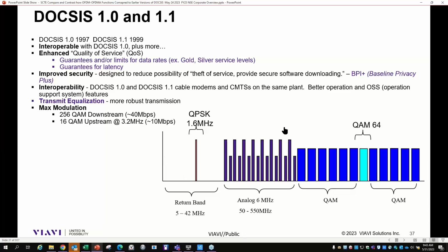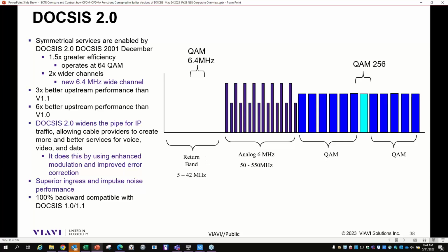Some systems used the upstream for video services, for analog, sending a video carrier upstream to another location and up converting those type of things. But primarily this was the DOCSIS capability of that, right? And then over time, the carrier became wider. So DOCSIS 2.0 came about, with the ability to do 64 QAM and a 256 QAM carrier. That was a big deal, right? Higher throughput on the downstream, higher throughput on the upstream, but it's still only one carrier.